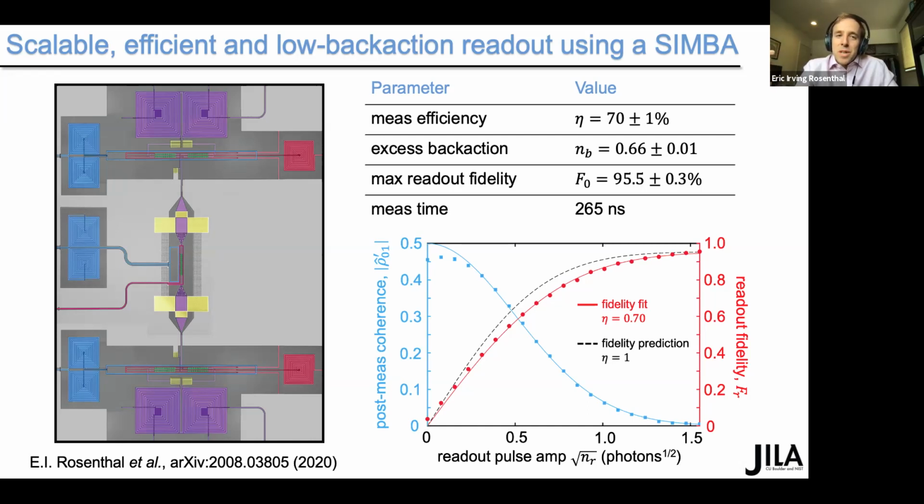And I think most of the loss in people's measurement chain comes from packaging losses. So if I have any reflection at the input of my circulator, the circulator routes it to some dissipative load, so it doesn't just mean my coupling rate is a little bit smaller. And so I really think that our efficiency in our field right now is limited by the packaging, not by the actual circulators. That said, I think it is very challenging to integrate them on chip with superconducting electronics, because they have these permanent magnetic fields, and your superconducting electronics almost always has some loops that you want to be very careful about the magnetic fields you put in.